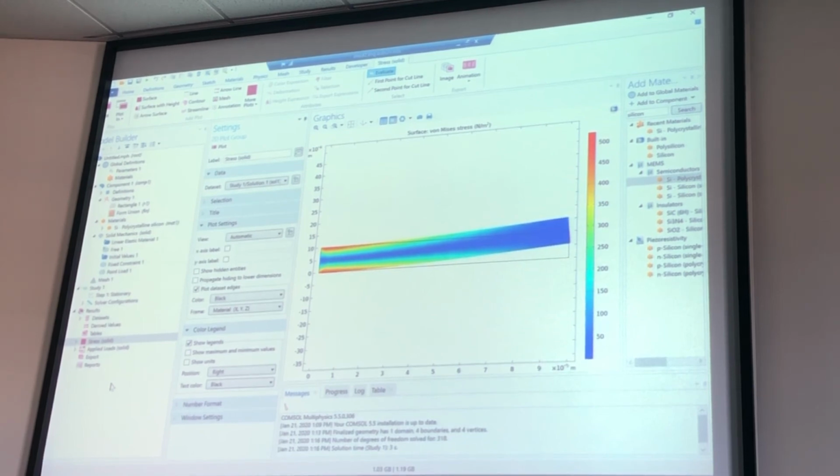Yes. I don't think the material set properly. It's telling me that I don't have the Young's modulus for this linear elastic material. Yeah, I don't. Do you still have an exclamation point? Yeah, the little exclamation points are like little warnings telling you, hey, something's not set yet. Yeah, I have that.